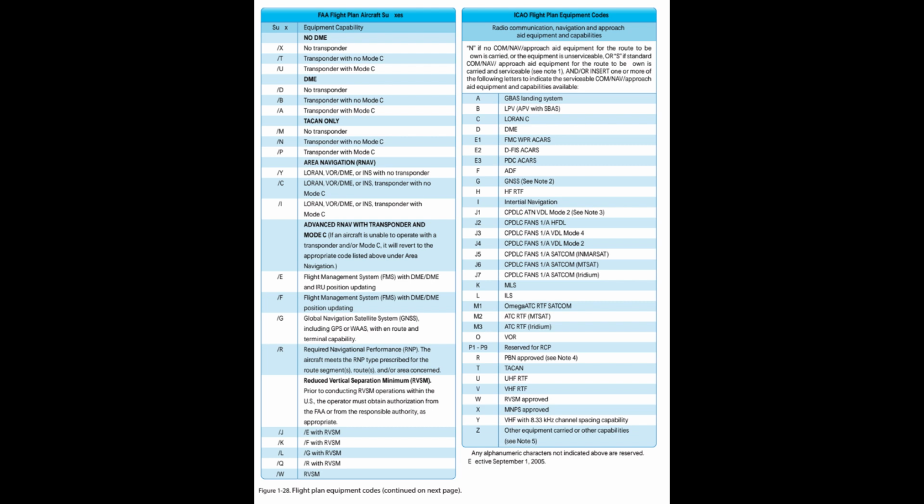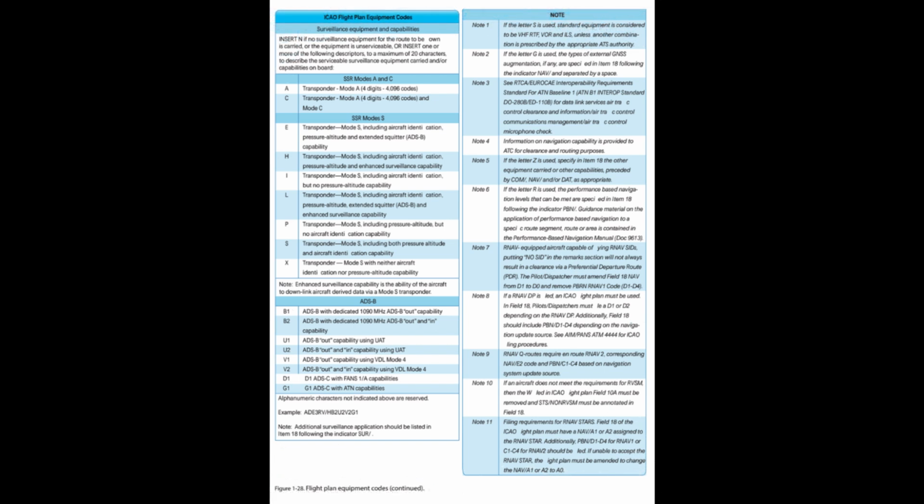While operating on RNAV segments, pilots are encouraged to use the flight director in lateral navigation mode. RNAV terminal procedures may be amended by ATC issuing radar vectors and/or clearances direct to a waypoint. Pilots should avoid premature manual deletion of waypoints from their active legs page to allow for rejoining procedures. While operating on RNAV segments, pilots operating RNP aircraft should adhere to any flight manual limitation or operating procedure required to maintain the RNP value specified for the procedure.